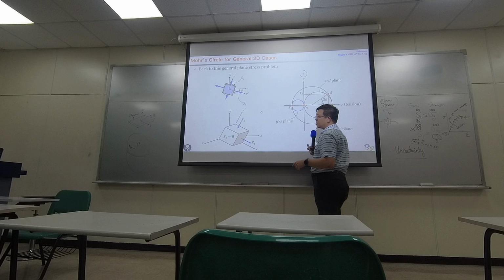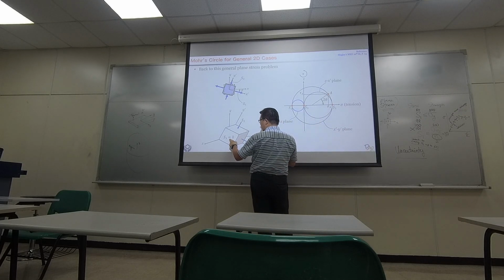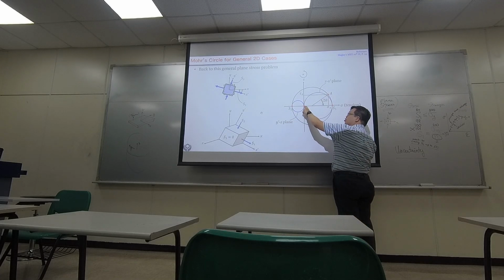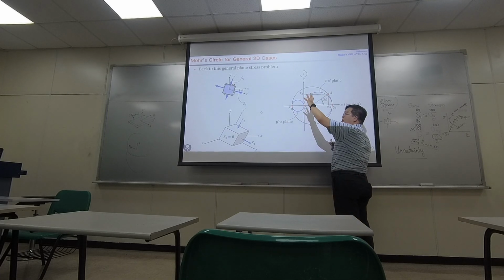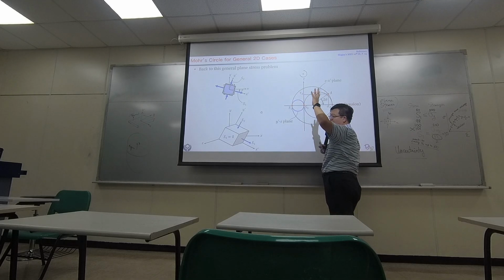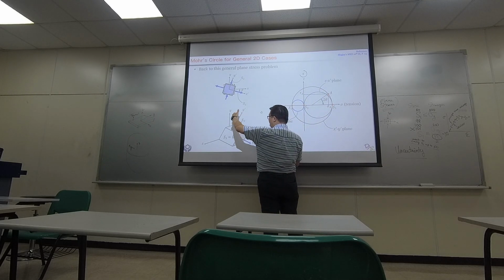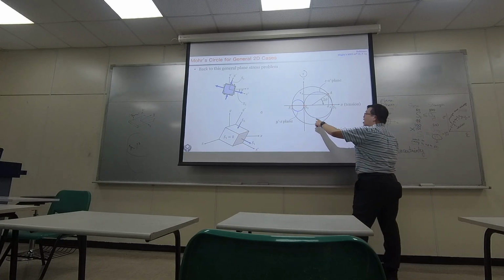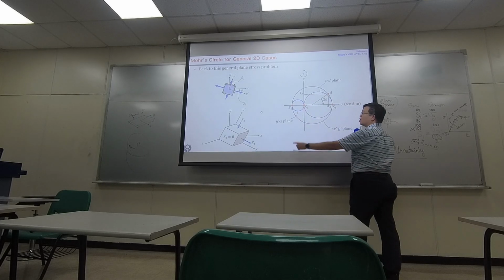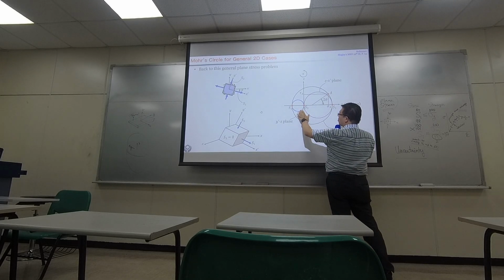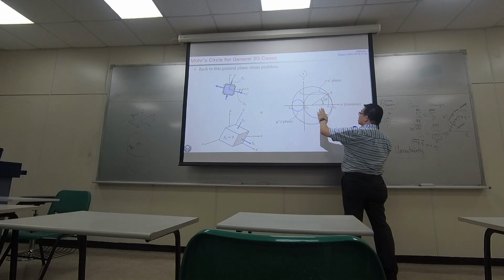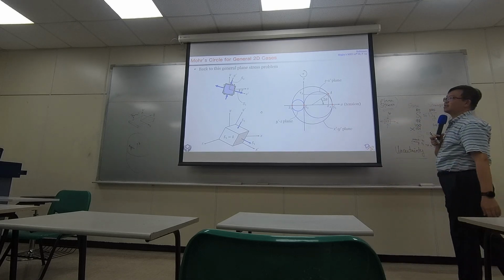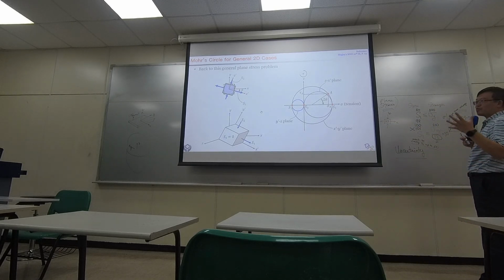But in fact, because your stress in the third coordinate is 0, there is a third principal stress which is 0 right here. And if you investigate the load condition in the YZ plane or XZ plane, you can draw more circles. At the end, you will have 2 more circles. This one represents the Mohr circle in the YZ plane, and this one represents the Mohr circle in the ZX plane. So actually, there are 3 Mohr circles.